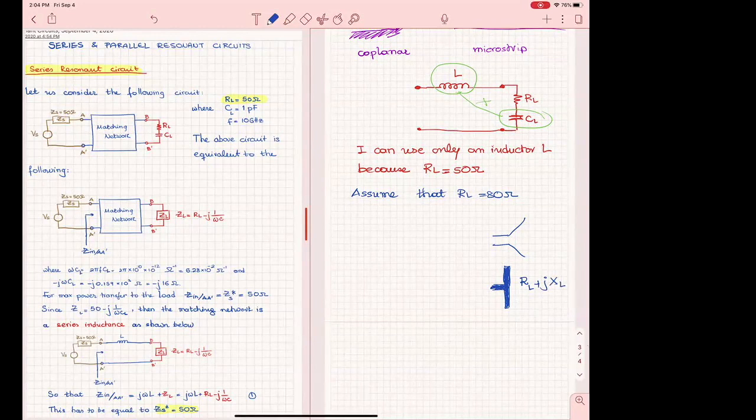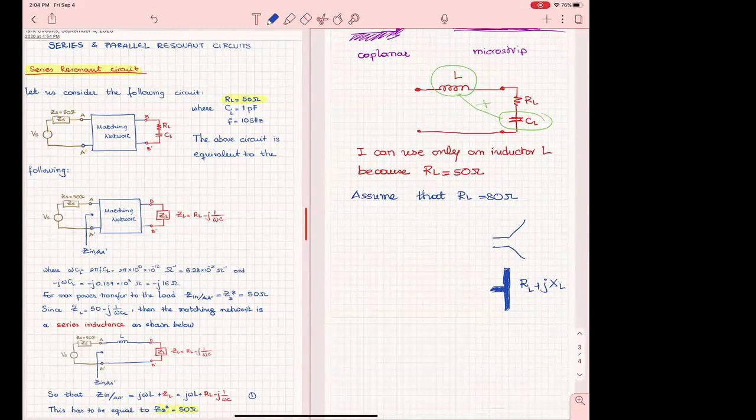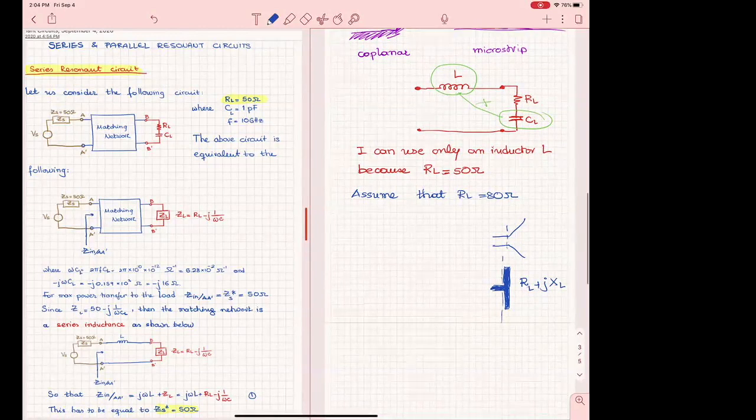then I would say that here, I will have to be careful where I'm using the stub, because I cannot go, the input to the antenna is right here. I cannot go and put a stub next to it because the stub is gonna look like this. So it's gonna impact my antenna. So I don't do the stub there.